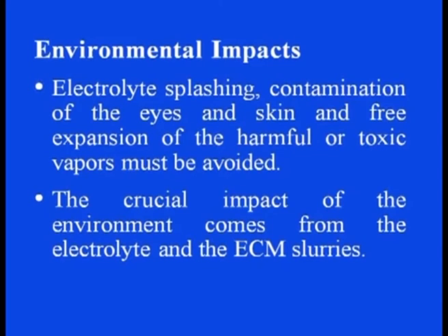Environmental impacts: electrolyte splashing, contamination of the eyes and skin, and free expansion of the harmful or toxic vapors must be avoided. The crucial impact on the environment comes from the electrolyte and the ECM slurries. Most of the time sodium nitrate fulfills the requirement of high removal rate and surface quality.